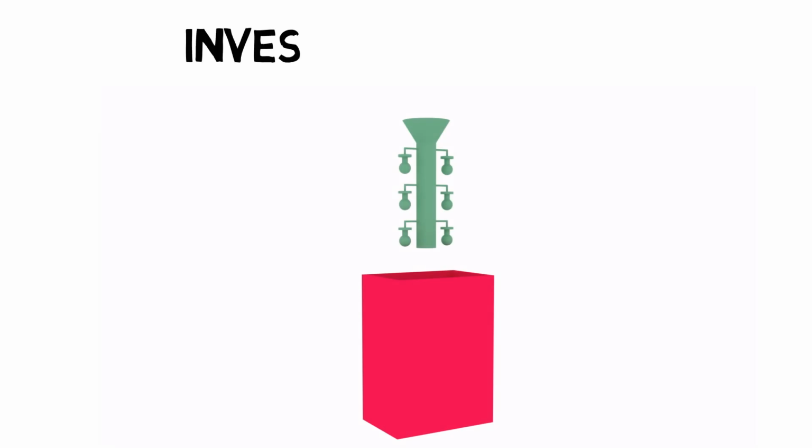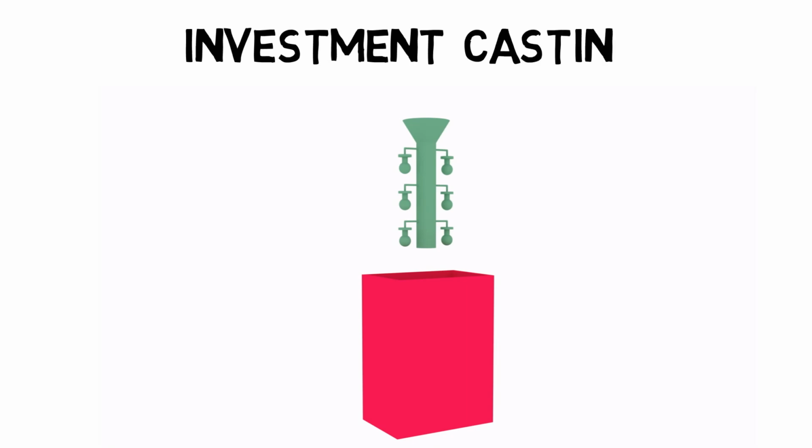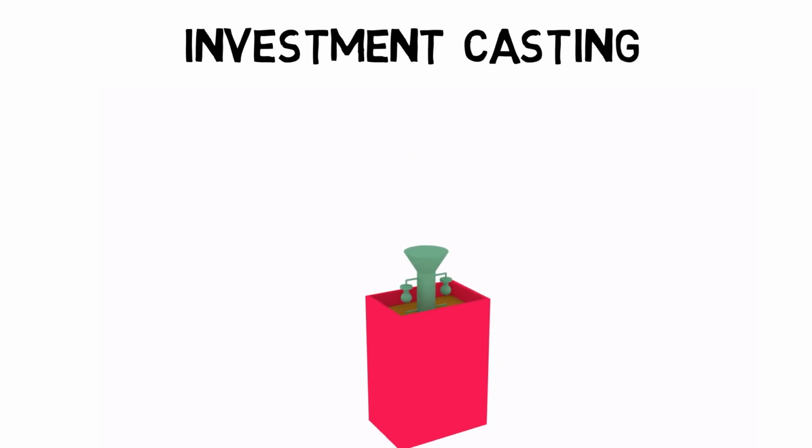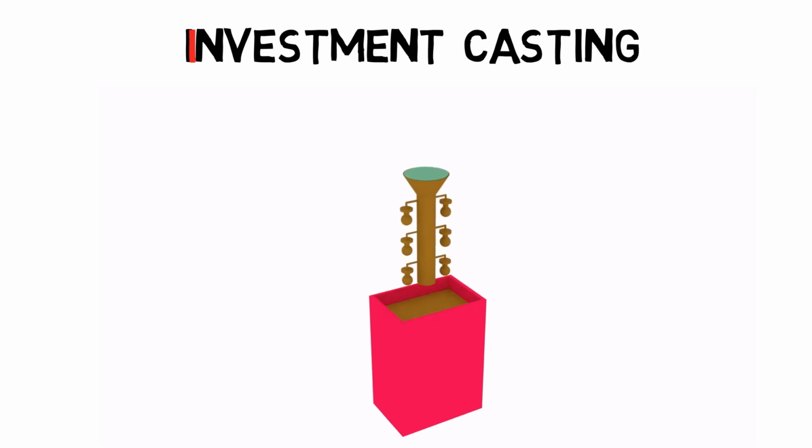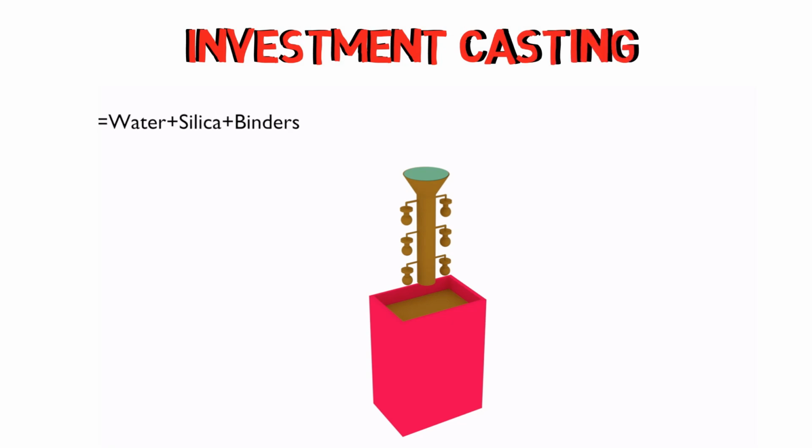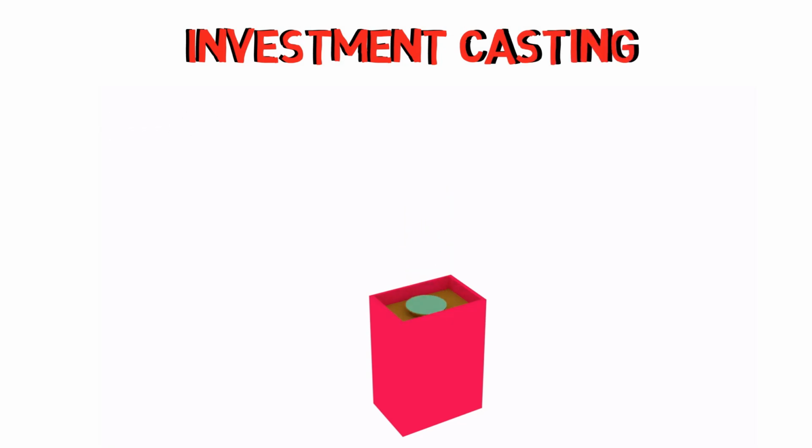A variety of small components like gears, cams, pipe fittings and many other machine components can be produced by the investment casting process. This coating of wax pattern with the ceramic slurry is termed as investment. Hence, it is called investment casting. In this process, first we make the patterns from wax and then we drain out the wax to have a mold cavity. Hence, this process is well known as the lost wax casting process.